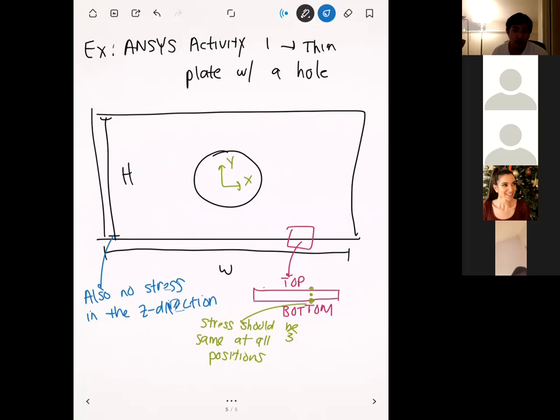And so if we mesh this geometry with quadrilaterals versus hexahedrons, the quadrilaterals per element are going to be a lot cheaper than the hexahedron ones, okay? And you can almost think of it like this, where say that we did try to model this with hexahedrons, right? So let me put a hex right here.